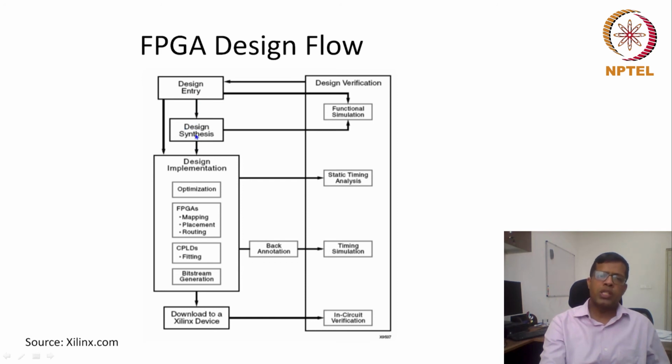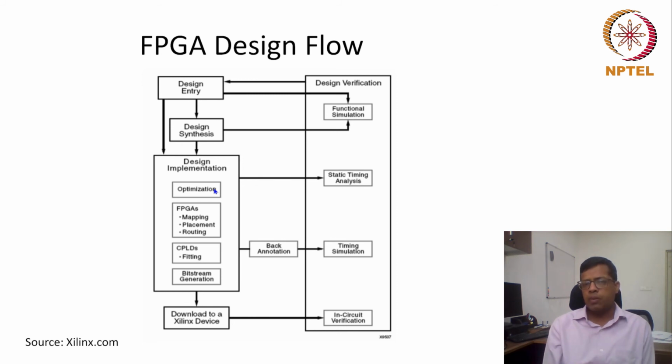So after doing synthesis, finally the design is represented using basic AND/OR gates, basic multiplexers, or basic elements. Then after that, first of all, some optimizations would be done. Optimization means logic optimizations or state machine optimizations. In logic optimization, we have seen how we can reduce the logic into a minimum number of gates, and in state machine optimization we have seen how we can reduce the number of states.